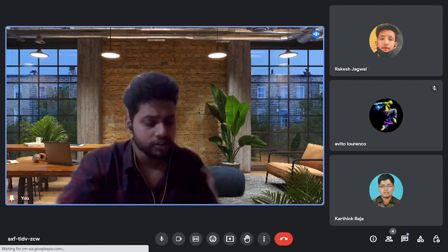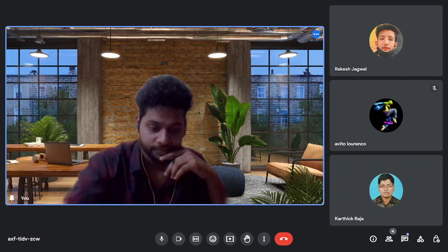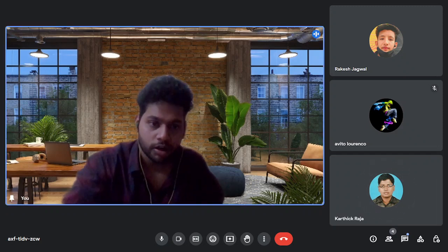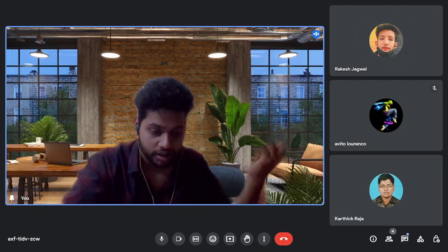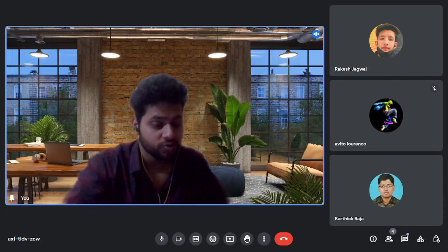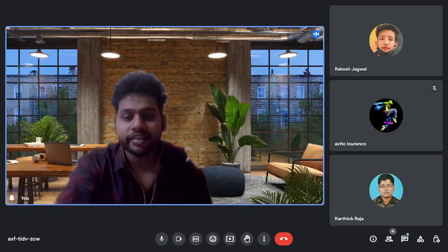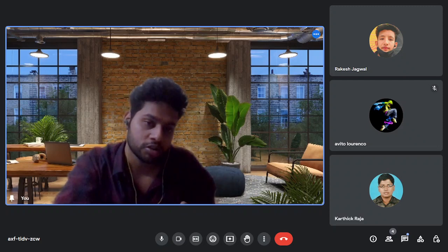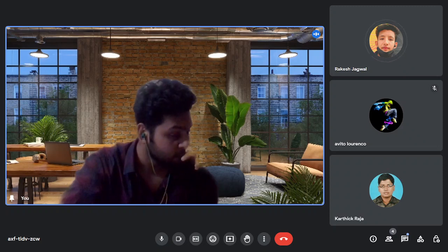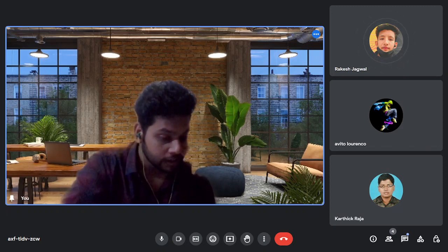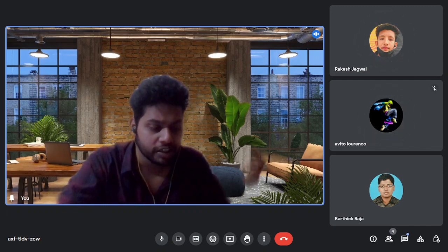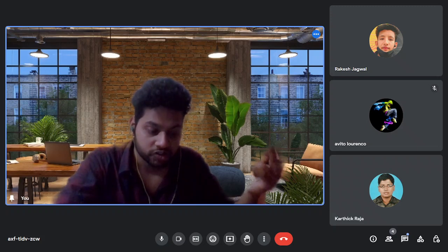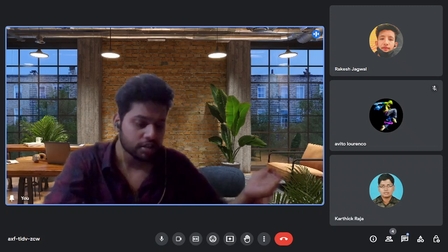If the ceiling fan is rotating slowly, there are several things you can check. The fan blades: make sure they are clean and not obstructed by dust or debris. The motor: check if the motor is working properly and not overheating, because if it overheats, the electric energy will mostly be converted into heat energy instead of being used to rotate the fan. The next is the capacitor, the component that helps the motor start and run. The main answer is the capacitor only.